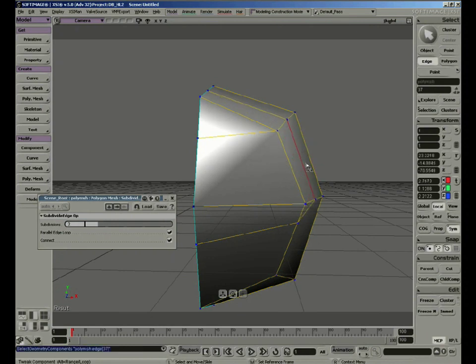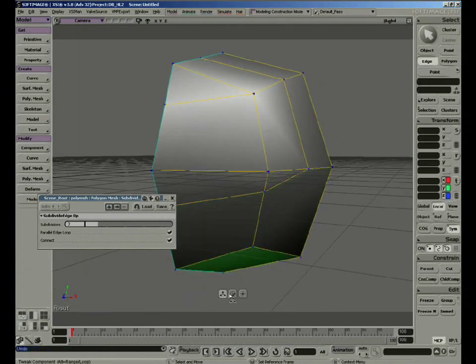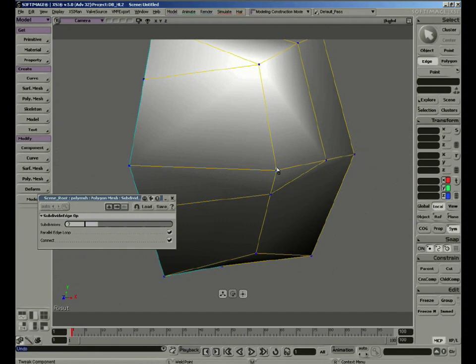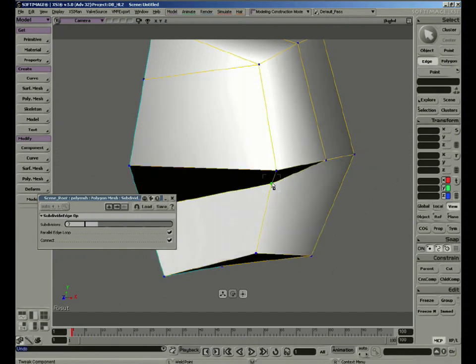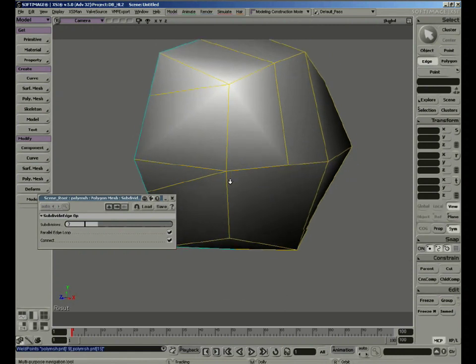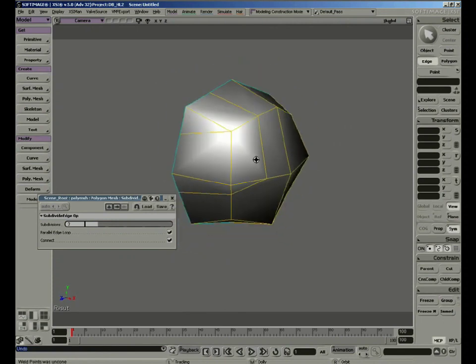The other way, without the option, will move freely and can deform the geometry. The third one is the Weld tool. If I want to join these points together, we just drag and select the points, and it will merge the points together. But let's hit undo for now.